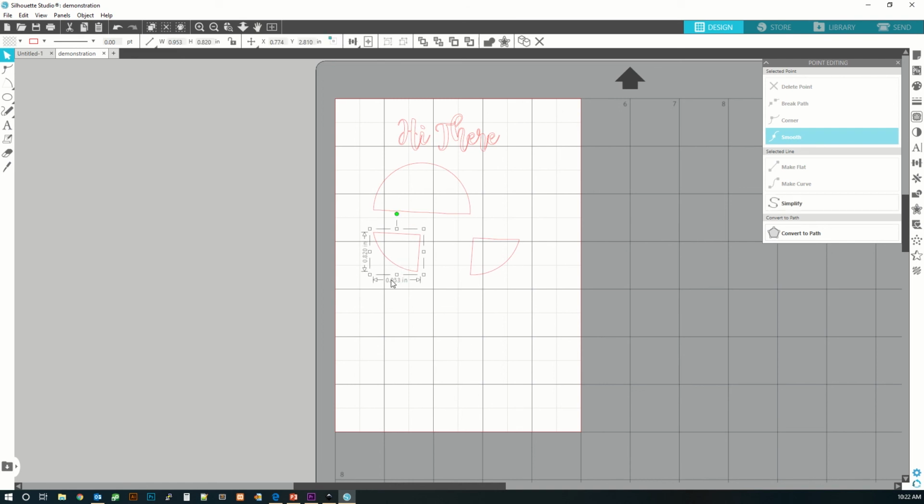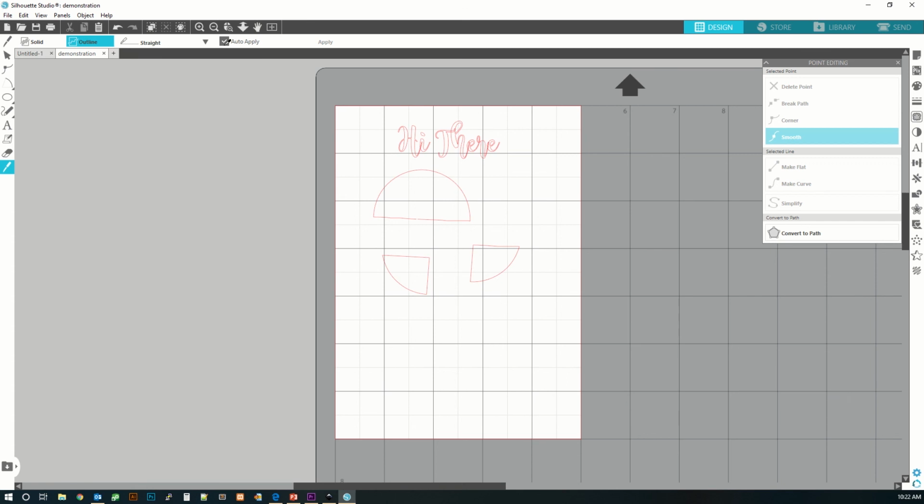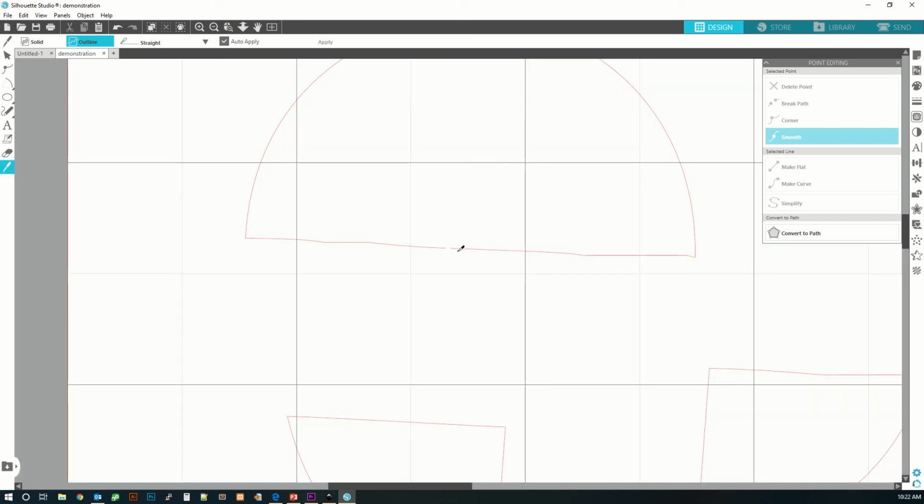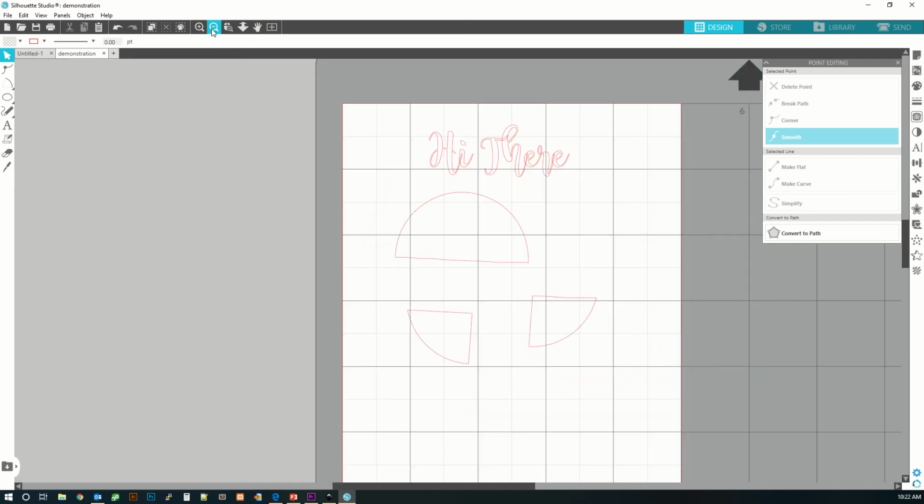By selecting the outline, you can see that it's only erased the outline of our shape and created a gap. The red dots indicate the gap. When you double-click the red dots, it'll close the gap for you if you didn't want that gap there.